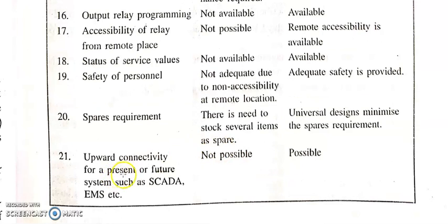And when it comes to connectivity to present or future systems such as SCADA and EMS, that is supervisory control and data acquisition, it is not possible there, but here it is possible. So in each and every aspect you can see the numerical relay has advantages. You can say this is the future of all power systems in the coming years.